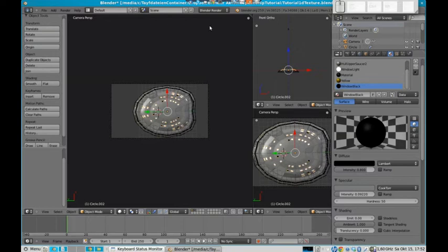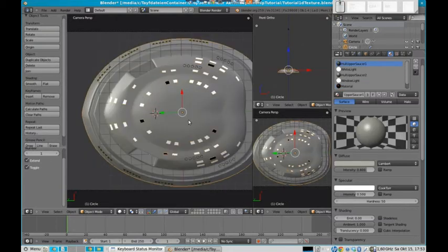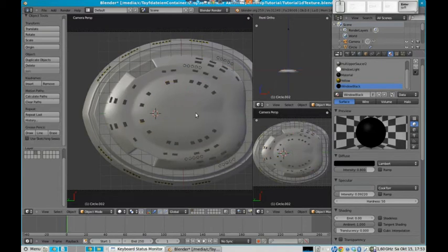Now another important thing to know is that we actually want to separate the windows from the other meshes. The windows should not be bump mapped, for example, and the windows should be emitting. And to be able to separate those settings, we will separate those textures too. So let's remove the hull part of our texture by going just to the windows. Where are the windows? Okay, the windows are not on a different layer right now, so let's select the windows and press the M key for moving them and put them to layer 4, where nothing else is right now.